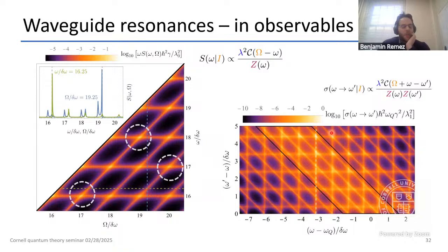Okay, instead of scrolling, I'll just say, so I've mentioned that this transition point happens when this ambient impedance matches the resistance quantum, right? And the debate is whether this point is actually independent of the circuit parameters. So there's some conflicting literature early on that says that actually, depending on if you have a junction with a certain EJ and EC, the critical point will also depend on EJ and EC, like what's the exact value of impedance you need to hit. And it's not a universal constant R_Q like I've illustrated here.